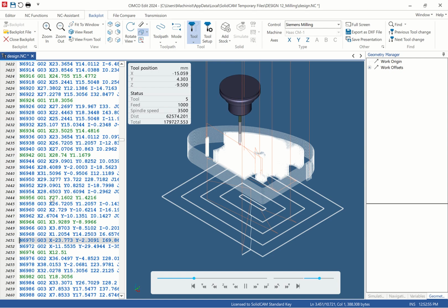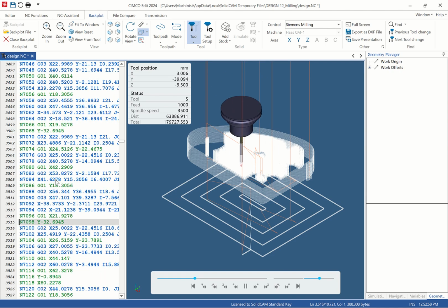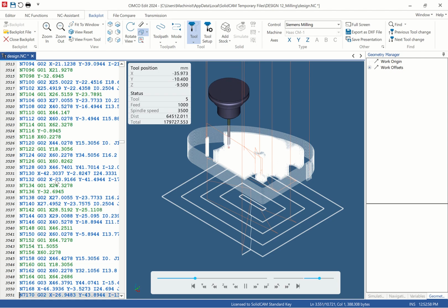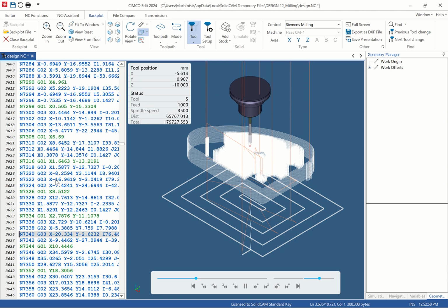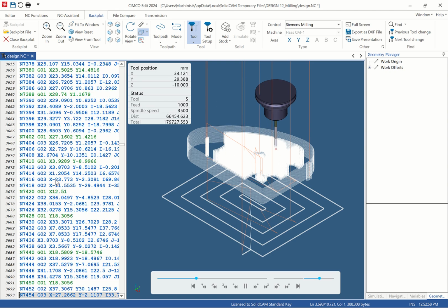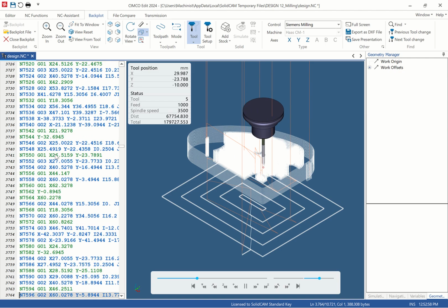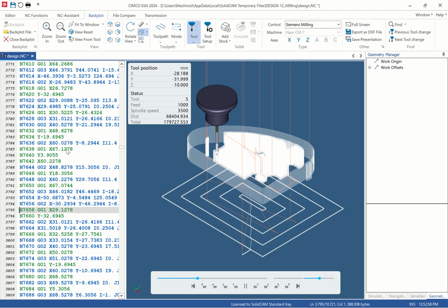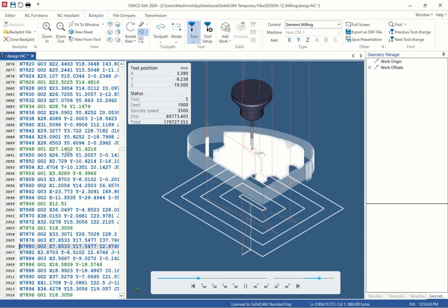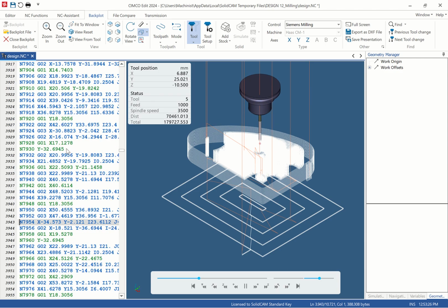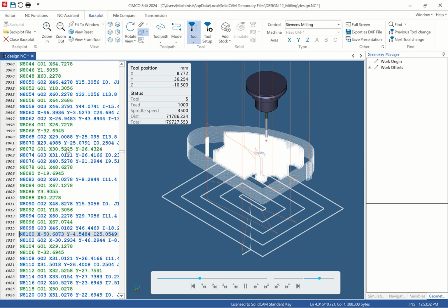So whatever you are seeing here is what you call G and M code, preparatory and miscellaneous functions. Because you need to understand how this language operates, how this language is used to control the tool movement or to control the machine table movement. So the CNC is just a computer numerical control where you're using coded instructions. These are codes, coded instructions to control how the table is moving, how the tool is moving to shape the stock into the desired part, product or output. So all these parts are interrelated.